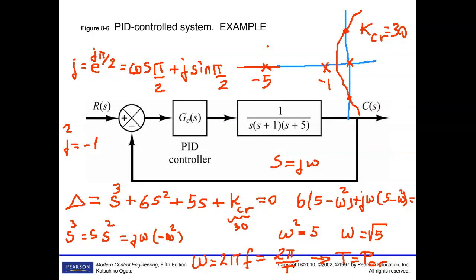Or you can just double click on the empty space. Then you can write, let's say, transfer function. This block will take the transfer function of your input. When you double click it, you can define your numerator and denominator here. Yeah, let's make it 165.